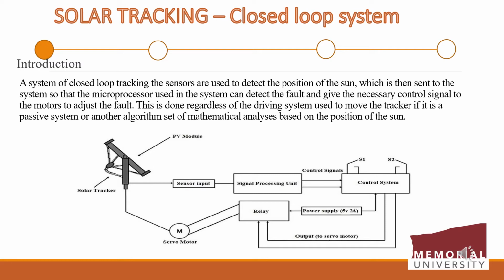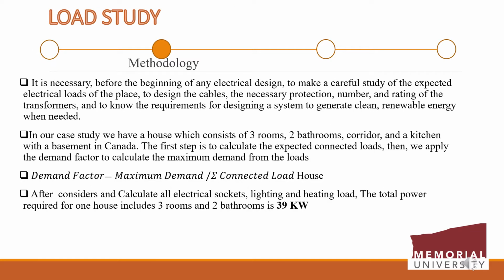Load study. It's necessary before the beginning of any electrical design to make a careful study of the expected electrical loads of the place, to design the cable, the necessary protection, number and rating of the transformers, and to know the requirements for designing a system to generate clean renewable energy when needed. In our case study, we have a house which consists of 3 rooms, 2 bathrooms, corridor, and the kitchen, with a basement in Canada. The first step is to calculate the expected connected load.